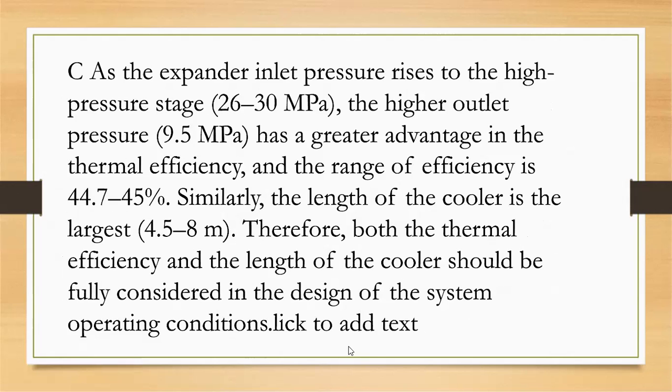And as the expander inlet pressure rises to the higher pressure range, in the before slide we considered the expander pressure between 22 to 26, and here we are considering an inlet pressure of the expander of 26 to 30 megapascal. The higher outlet pressure of 9.5 megapascal has greater advantages in thermal efficiency, with a range of 44.57 to 45%. Similarly, the length of the cooler is largest, 4.5 to 8 meters.